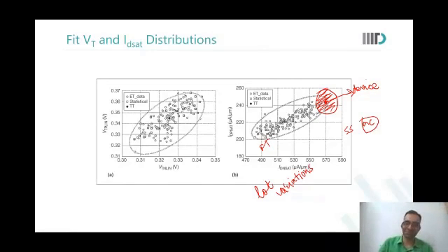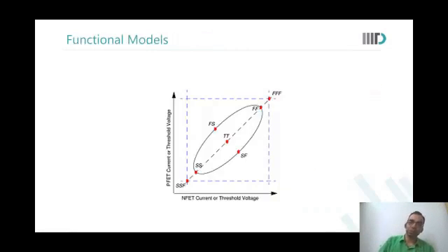Okay. So in addition to these TT, SS, FF things, we also have what are called FFF and SSF lots or points. They are essentially the result of when I run Monte Carlo on FF and SS. I see that the worst case NMOS and PMOS combo can happen over here.